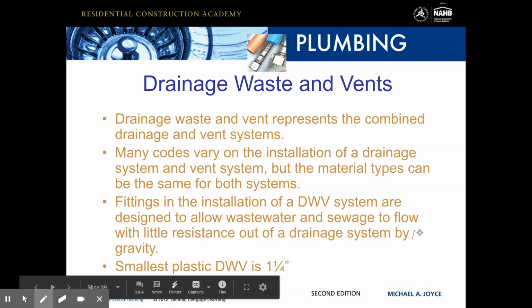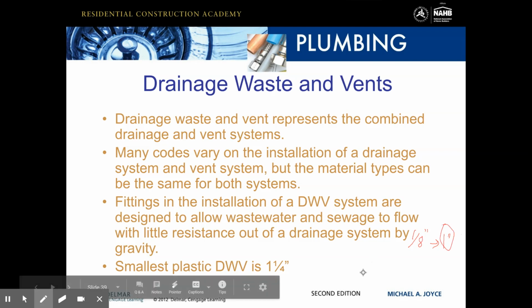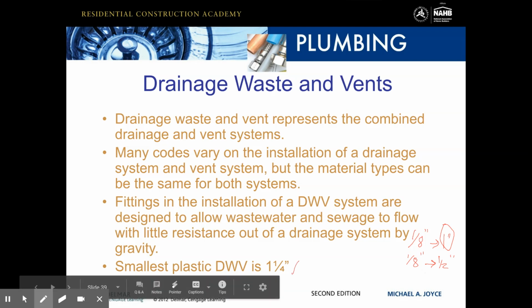Typically, these go from 1/8 inch to an inch per foot. An inch is really steep. Most common that you'll see would be 1/8 to maybe half. The smallest plastic drain waste vent available is 1.25 inches.